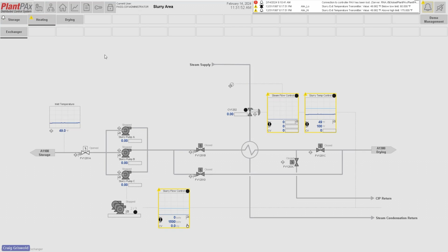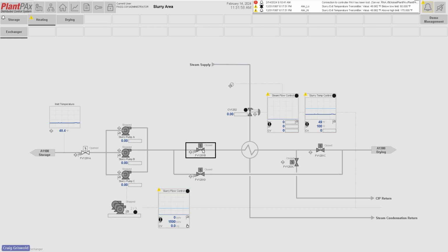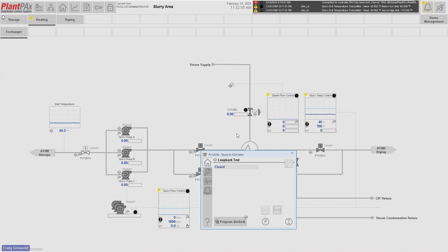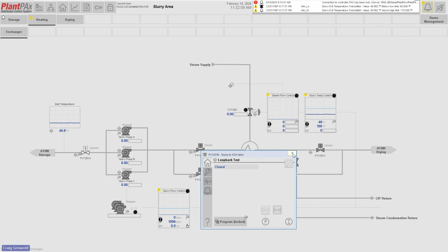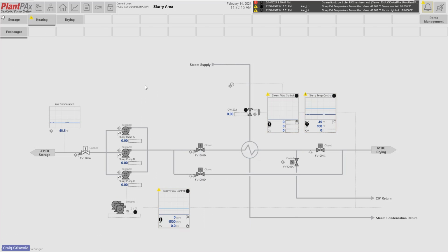So my shortcut in FactoryTalk View Studio SE, I pointed at the emulate controller, and now I can start testing my HMI, my faceplates to validate communications, alarming, do your basic testing prior to either deployment or getting that physical controller.